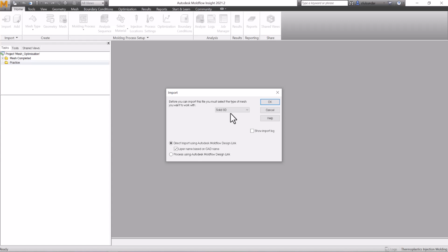Dual domain mesh always lies as the base for the 3D mesh. Well, there is an option to directly import the CAD model and run the simulation. The algorithm automatically converts that surface into the 3D mesh, but in the background it converts the CAD model into the surface mesh and then gets into the 3D layer mesh. We'll also see some of the options while importing.